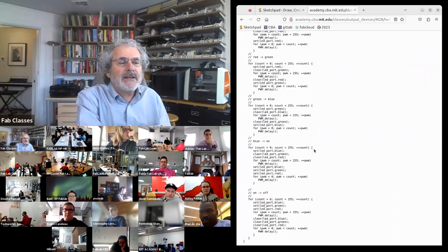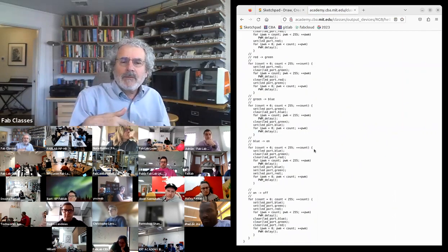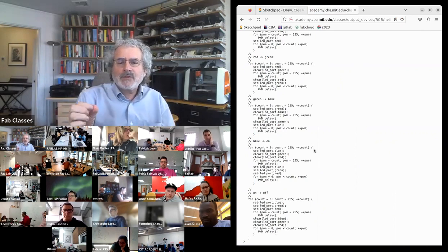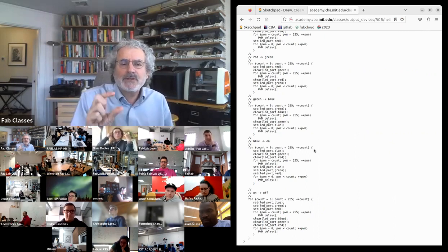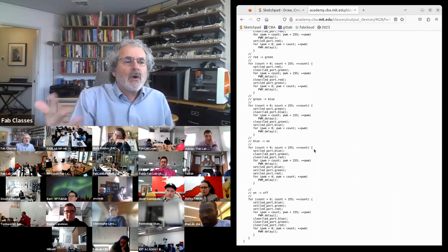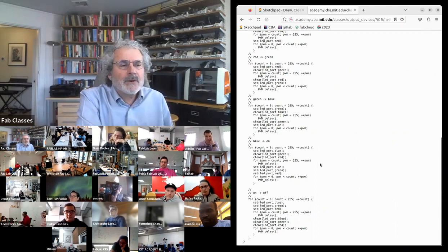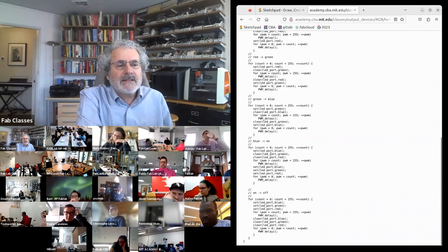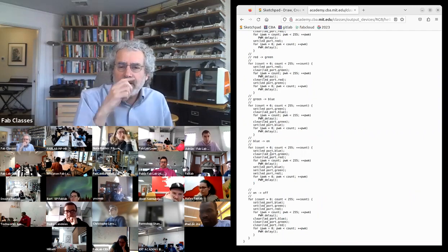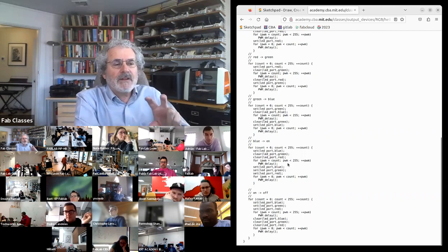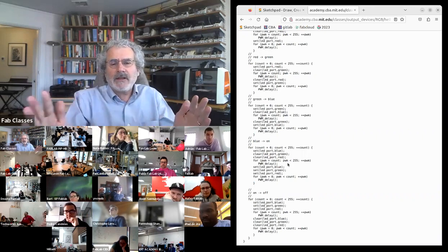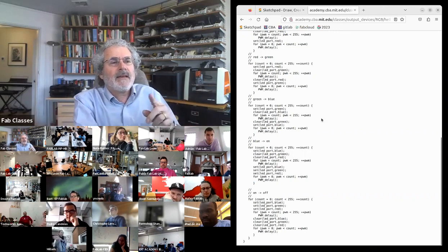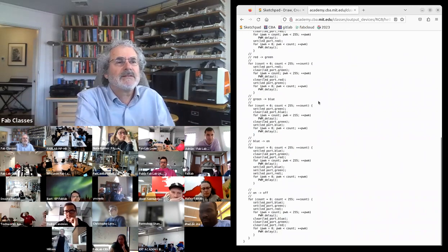So in this example, we'll talk more about this. The processors we're using have modules in hardware that can pulse width modulate, where you just tell them the rate to modulate, or you can do it in software. So here I have a loop, and in stages, I pick which pin to turn on, and then I vary the time I'm on versus the time I'm off. And then I'm slowly varying the on versus the off time, and then I'm cycling between the different pins.